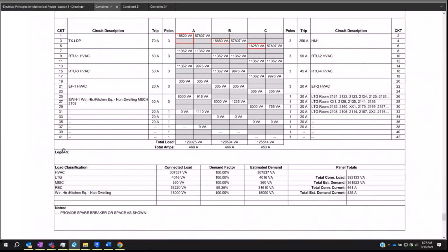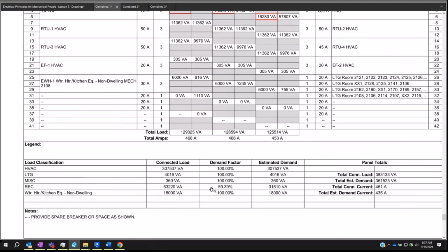On top of that, the way I did it is incredibly convoluted and complex because I followed the NEC to the letter, to the T, and I've got a ridiculous amount of load classifications because that's how they did their load calcs in the front end of the book. I'd have to remember where it was. 220. There we go. In Article 220, it tells you how to come up with the final number of your service. And the demand factor is like putting diversity to your panel. Exactly. It's exactly what it is.